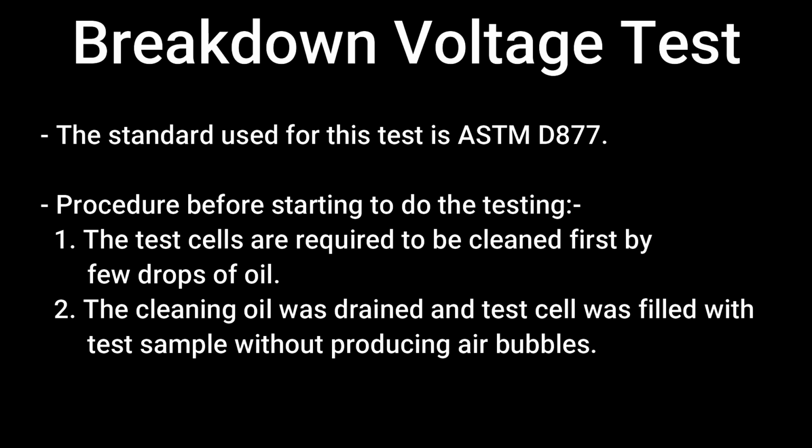Procedure before starting to do the testing: the test cells are required to be cleaned first with a few drops of oil. The cleaning oil is drained and the test cell is filled with the test sample without producing air bubbles.